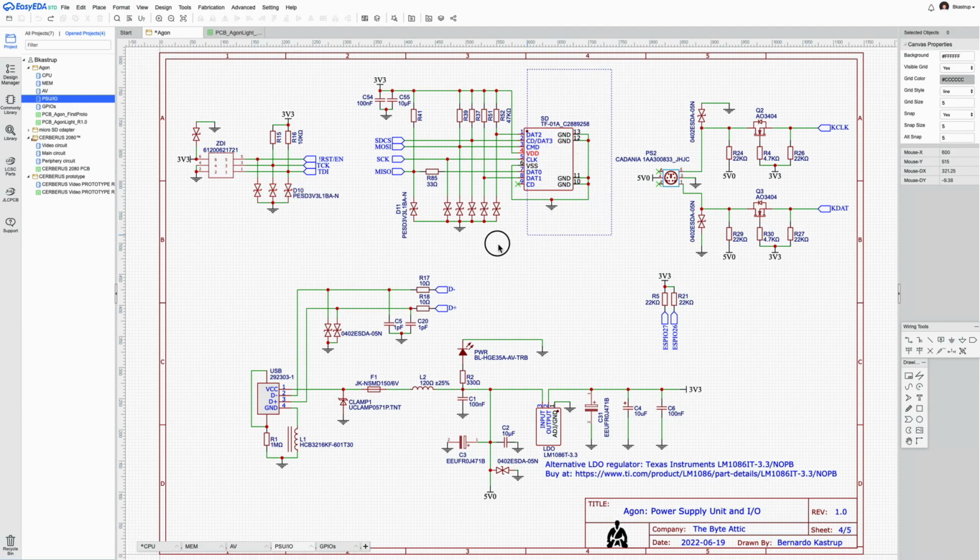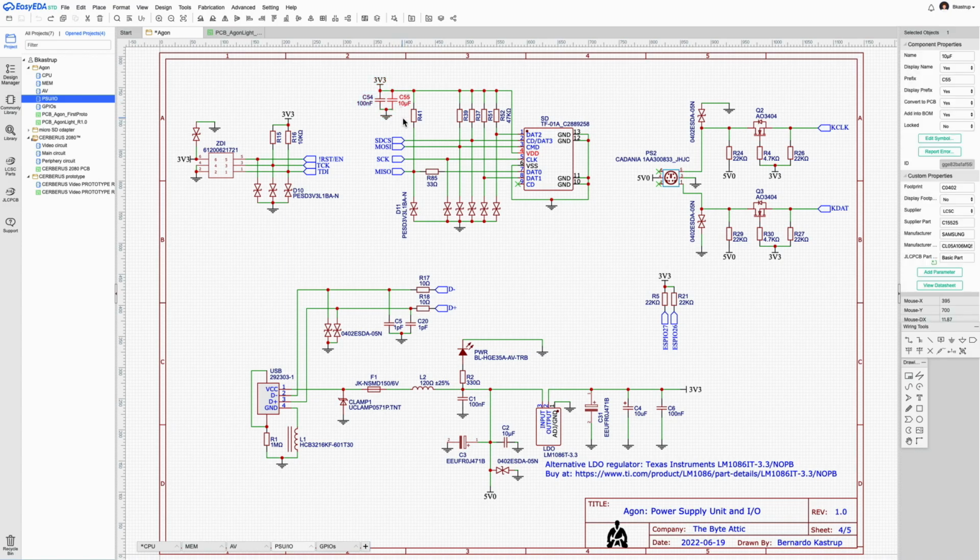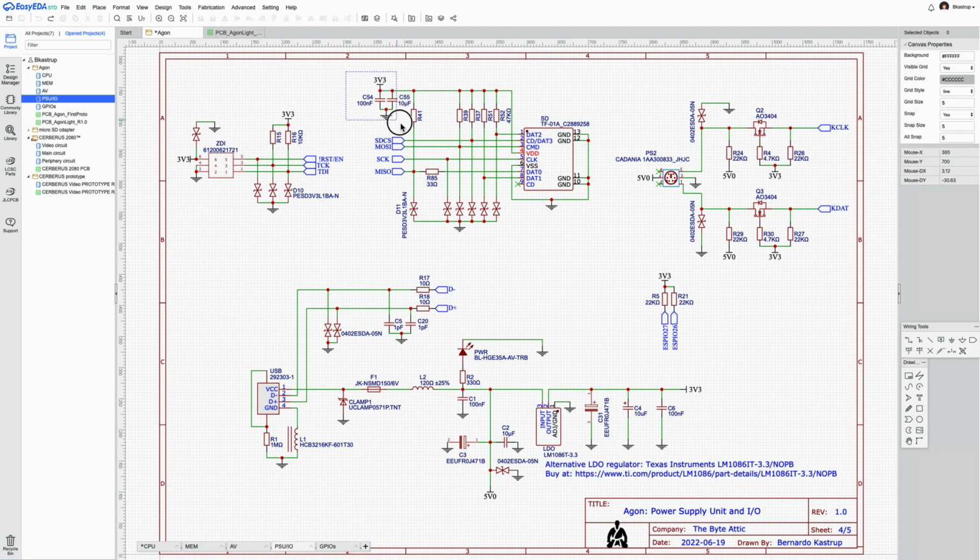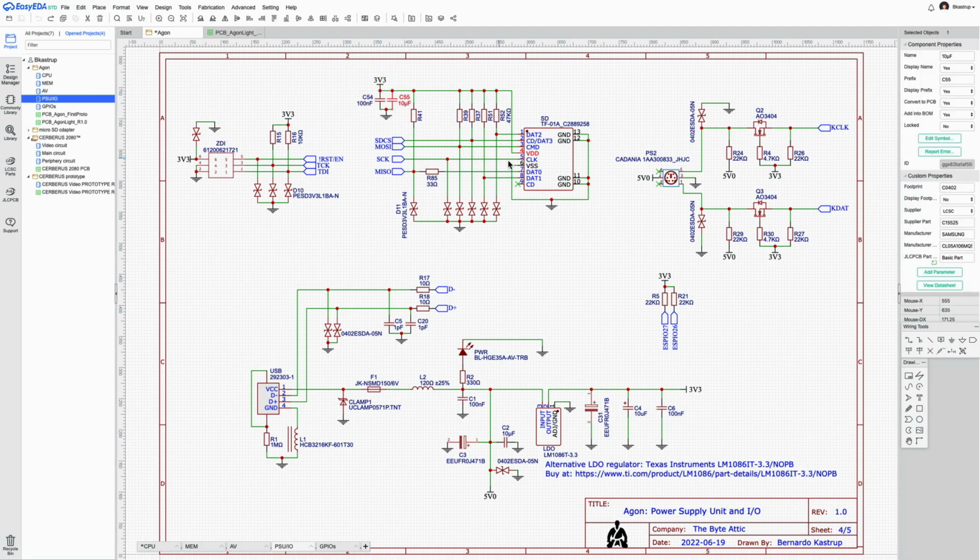This is the micro SD card connection circuitry. You have pull-ups, and you should have pull-ups. These are bypass capacitors to make sure the power level is correct, because you need to feed power here, VDD. You need to feed power to the micro SD card. So this ensures the power levels the card sees. The micro SD card is not just memory. There's a circuit in it that needs to be powered on. So you want to stabilize the power seen by the card.